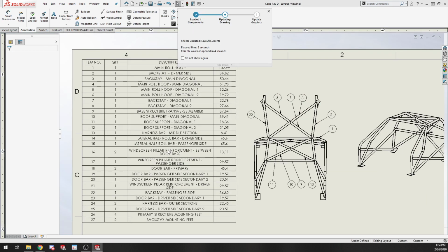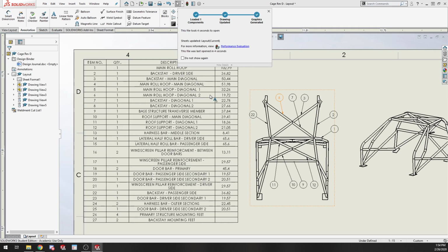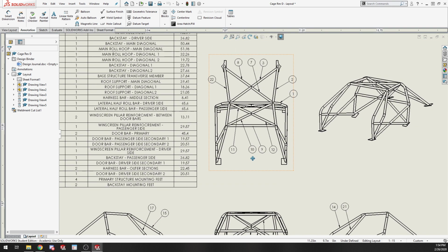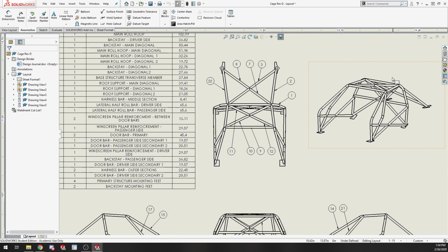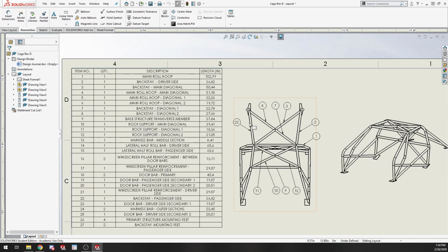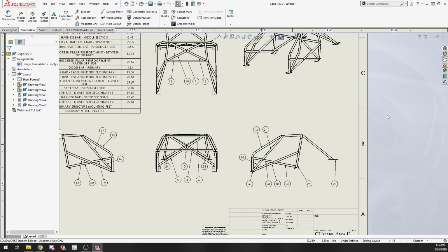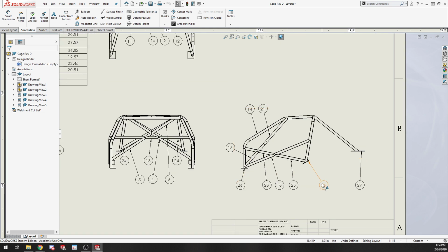We go and create an actual bill of materials. Looking at this last week, it gives us the lengths of the tubes that we start out with. So even for something complicated like this roll hoop, it gives us the length as it goes up, over, through all the bends. And so when I go to cut my tube out and bend it up, I just cut to basically 103 inches, and I know that I'm going to have enough tube to make all those bends in my tube bender. I don't have to bend the tube up and then fit it up and then figure out how much I have left over.